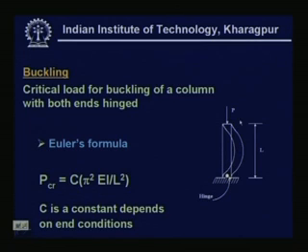We won't be discussing much about buckling. The only thing we would like to say at this moment is that it is a sort of stability issue where stress and other things are not coming into the picture. Basically, when you have a very long slender column acted upon by a vertical load, as shown in the figure, just given as P, this slender column can have a tendency of bending like this, which we call buckling.